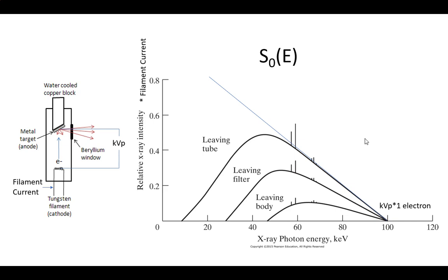Then what we're going to do is we're going to put a cup around it. Now the reason why we put a cup is to focus things. So imagine I just had the wire there all by itself. We're going to impose a voltage which will start accelerating in that direction. But if I'm aiming at a really big target and it's all the same voltage range, it could pretty much go anywhere. Right? So you can imagine, I don't just want it to go anywhere on the opposing side. I want it to hit the angled part of my edge.